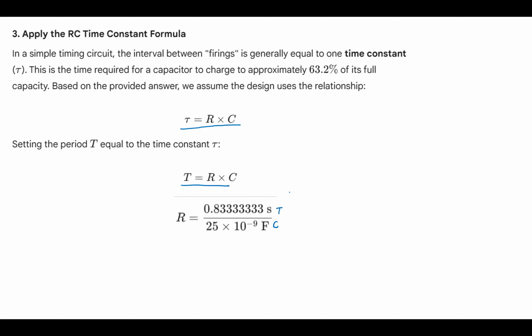So this problem is not exactly solved, but what we can do is, as a ballpark, we assume that it takes time RC to charge. Remember that in the charging case, RC is the time constant to fill the capacitor to maximum charge.